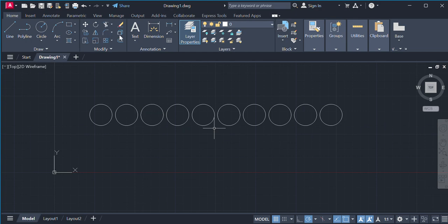Okay. So I'm just quickly going to touch on the freeze layer as well. The on, off, or the freeze columns, they work exactly the same way, but I found that when I'm using the on or off, it slows down my laptop or my AutoCAD quite a bit compared to when I'm using the freeze command or this freeze column. They work exactly the same way because it's essentially a layer I don't want to see anymore, whether permanently or temporarily, but for the purposes of the time that I'm working on it, freeze works just fine.